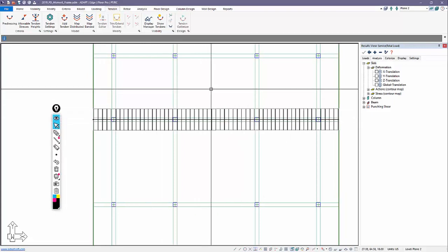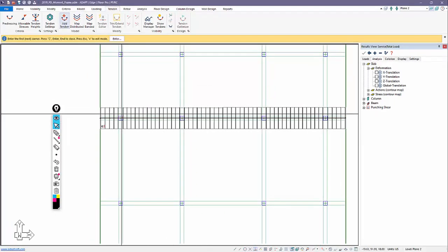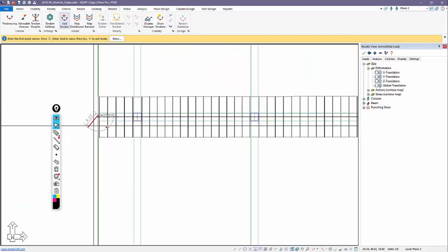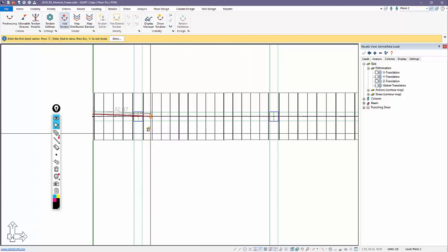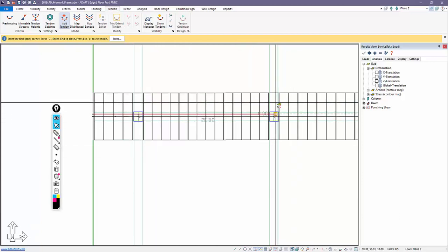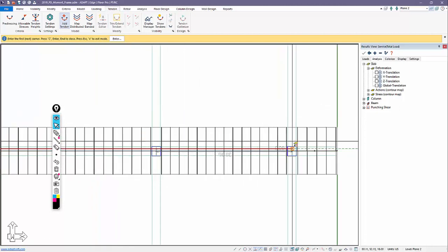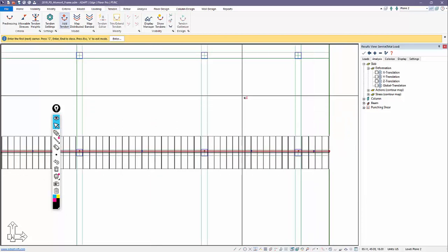this particular strip. I'll go ahead and add a tendon. I'll use snap to nearest just to snap on this slab edge, and I'm also going to use snap orthogonal so I can just align this nicely along the X direction path. I'll turn off these two snap options and then snap to perpendicular, press enter to close.